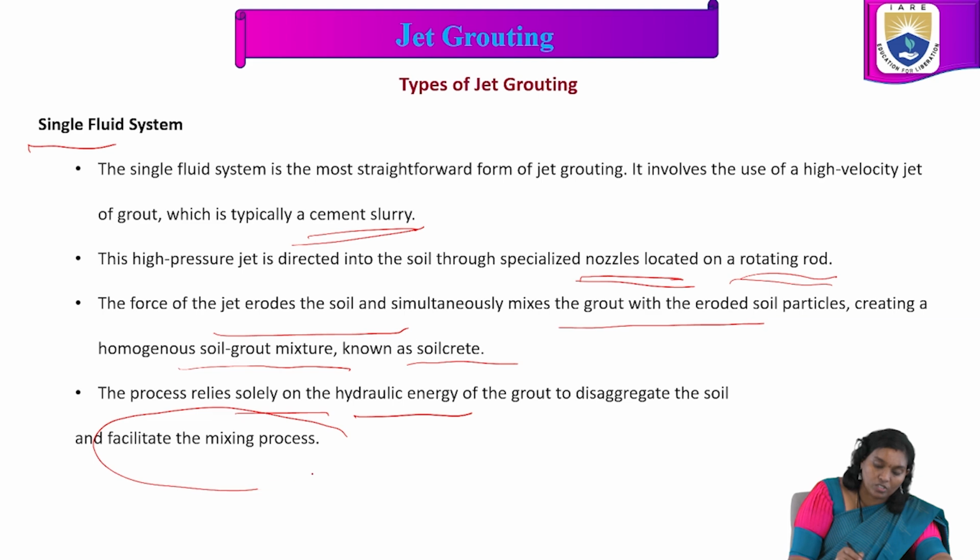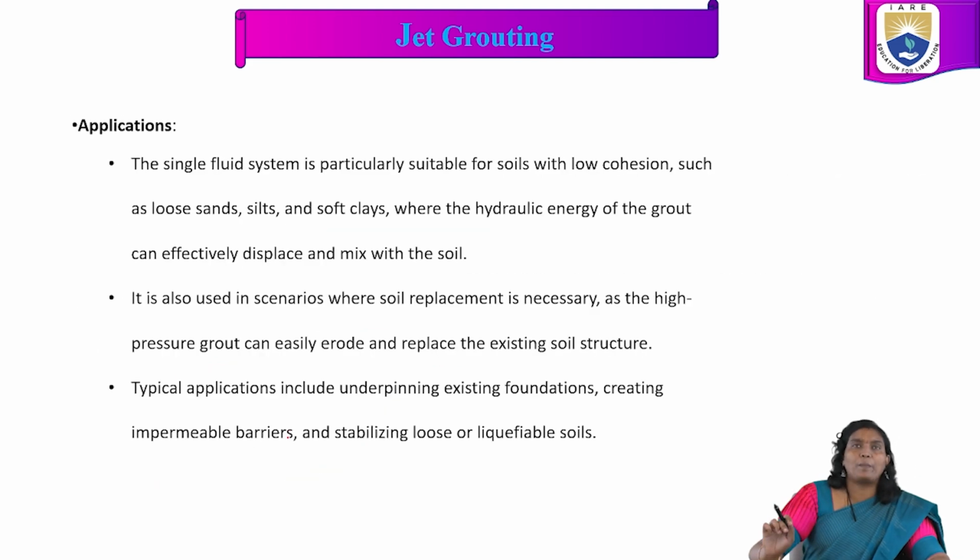The single fluid system is particularly suitable for soils with low cohesion such as loose sands, silts and soft clays, where the hydraulic energy of the grout can effectively displace and mix with the soil. This is one of the conditions in which we use this jet grouting type.